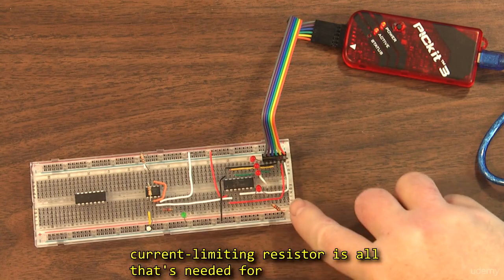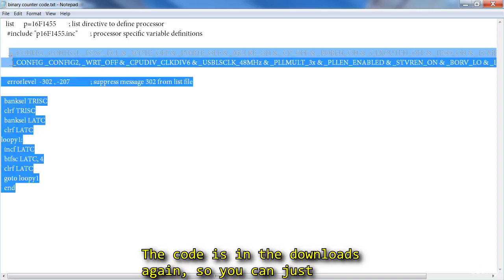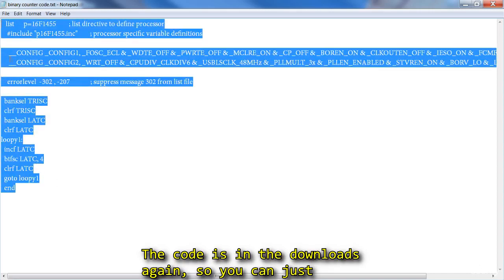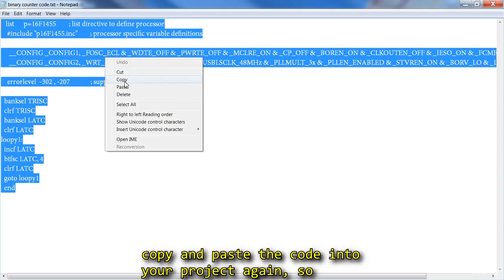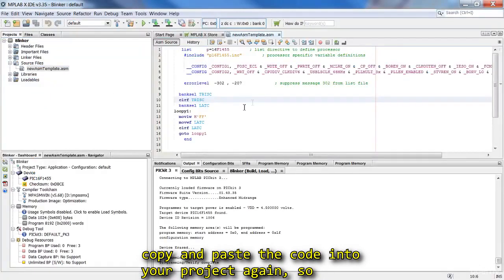So we're going to wire the LEDs on the output of port C again. To make these things simple, we'll use the least significant nibble, bits 0 through 3. A single current limiting resistor is all that's needed for all 4 LEDs. The code is in the download section again, so you can just copy and paste the code into your project again.